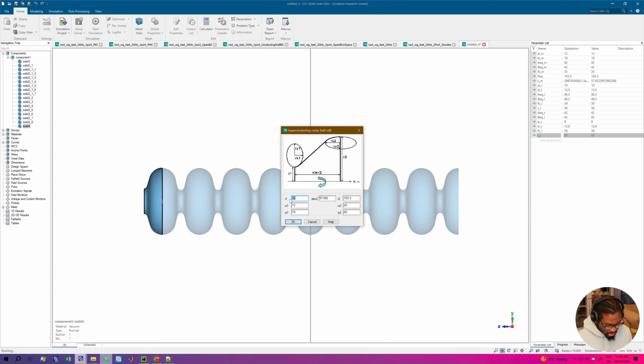Nope, I do not want to intersect. And now I move it by minus 8 times LM plus LR. So if I preview this, I still shouldn't rotate, so translate. I should have copied that. 8 times LM plus LR.